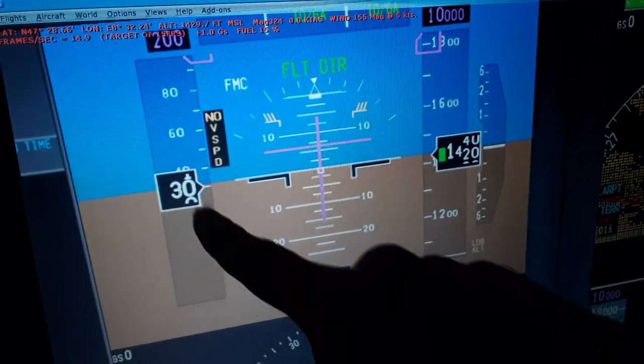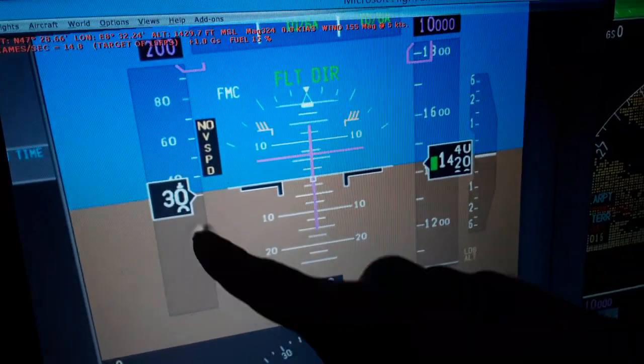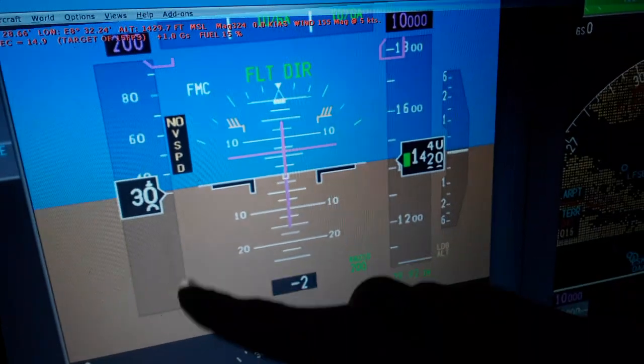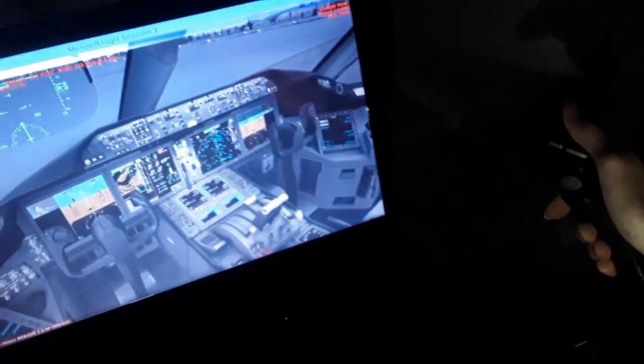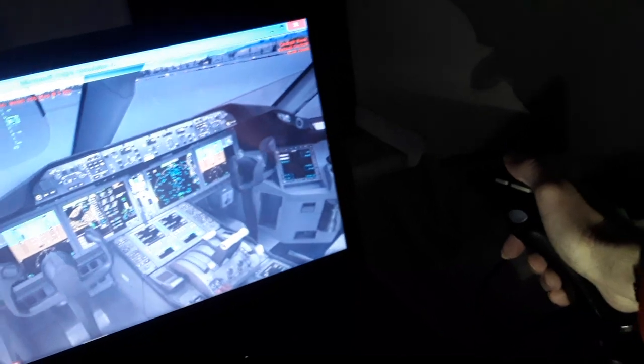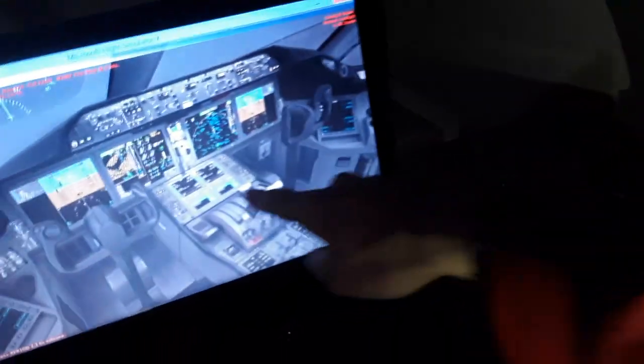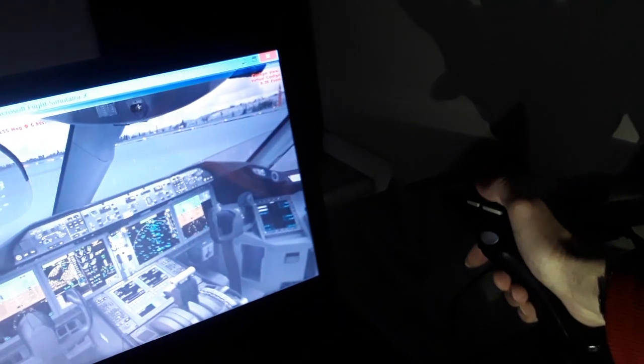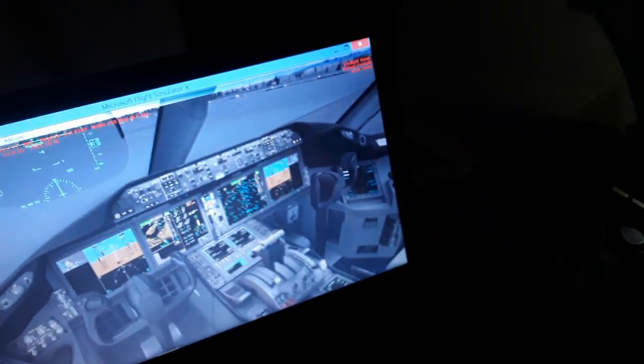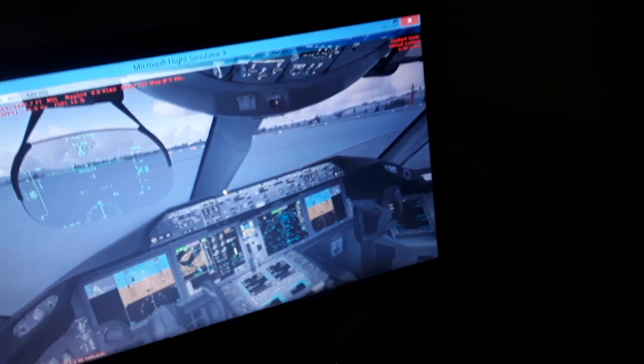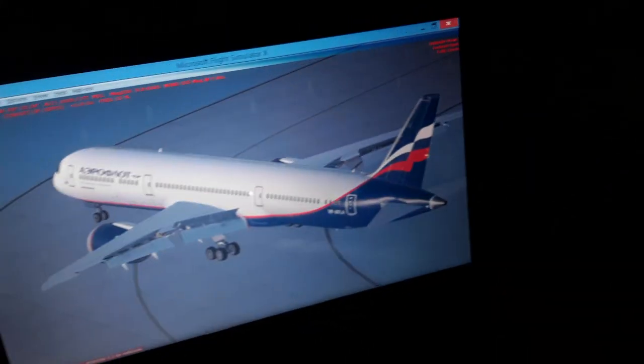Just below the airspeed indicator when we fly, we have a red and yellow or amber indication. We have the stall speed. We need to avoid stalling the airplane. So we press the side stick down when we see the stall coming in, or the yoke of the Boeing aircraft, and also apply more thrust afterwards when you have decreased your angle of attack. You can monitor the angle of attack of the aircraft or see outside. So this is the stall avoidance.